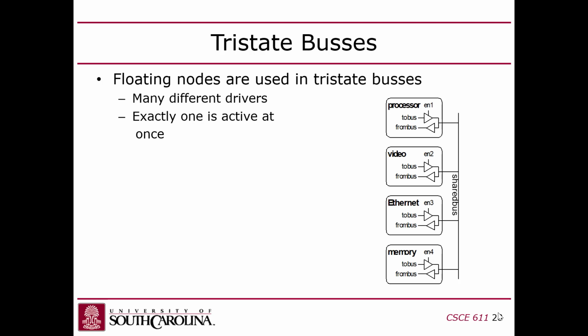Likewise, I can use this bus for input as well. And so I have another tri-state going the opposite direction if I want to read something from the shared bus as opposed to writing to it. Everyone with me? Yeah, that's a tri-state, and again, that would be a Z.